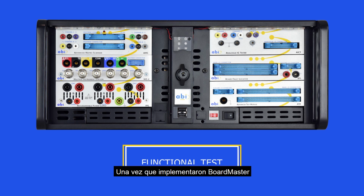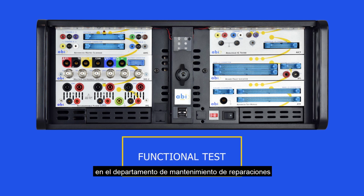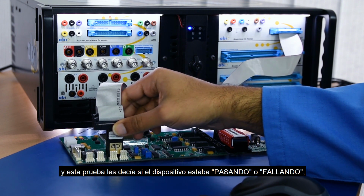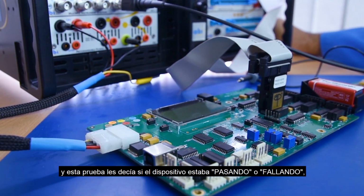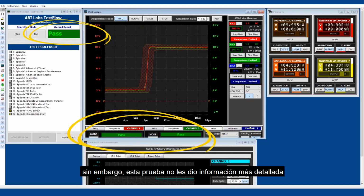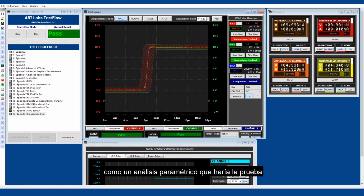Once they implemented the BoardMaster into the repair and maintenance department, they were carrying out a functional test using the AICT module, and this test was telling them whether the device was passing or failing. However, this test did not give them more detailed information like a parametric test would do. So in that case, they implemented the MIS4.